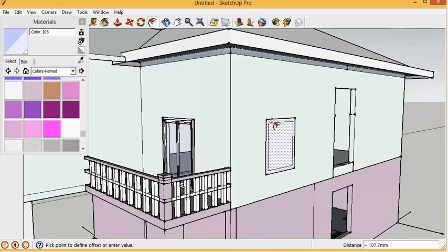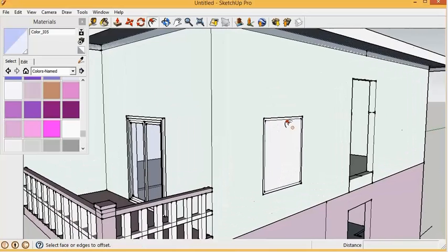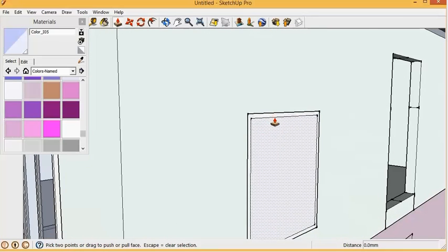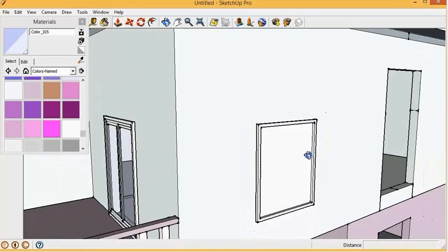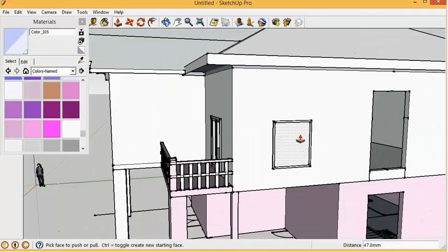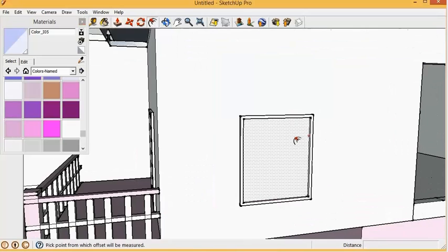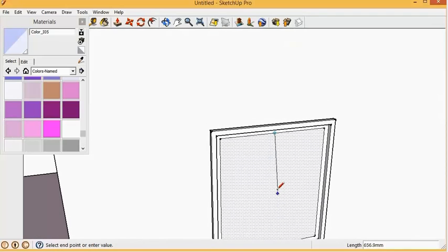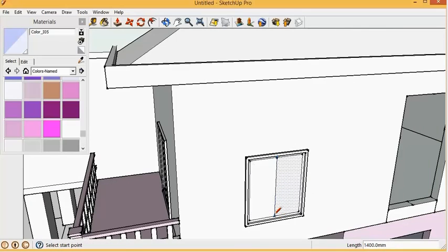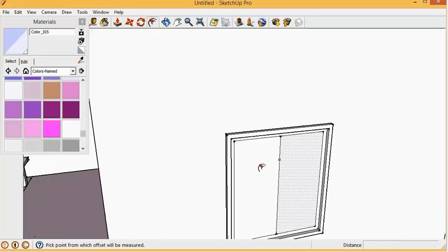And for that, we need to angle the roof along the other direction. So again, we can do the same with our protractor. The pitch of the roof is going to be the same. So that number was 18.5. So now that I have that, I need to find a way to get this line projected over here to the peak of the roof.